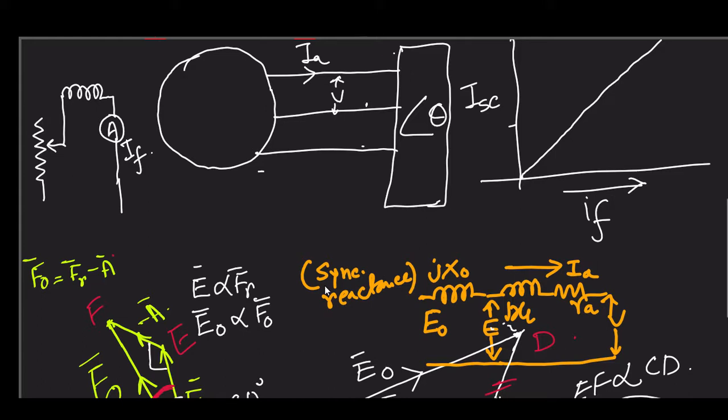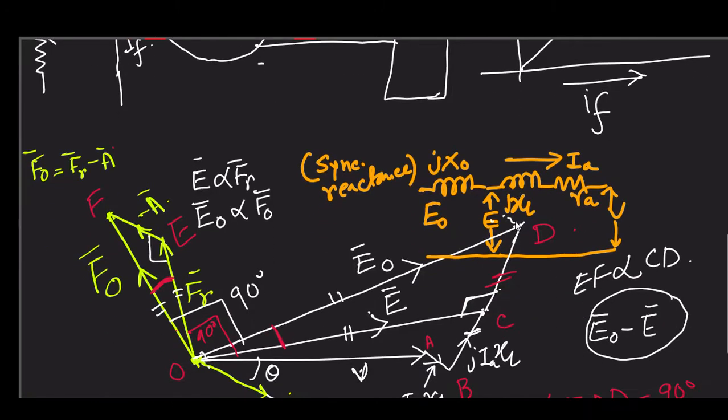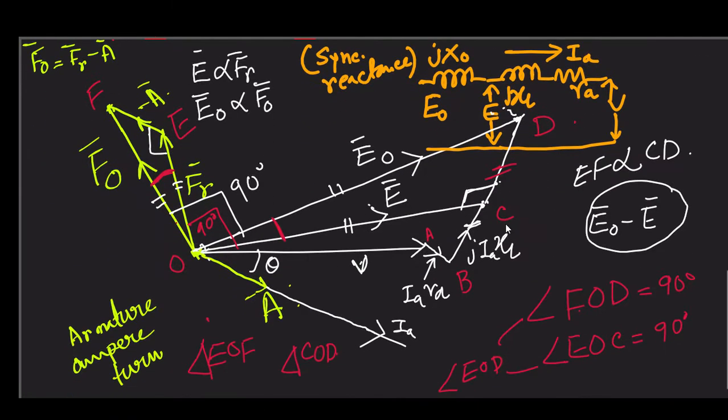As we know, the synchronous machine stator winding can always be represented by means of a resistor and an inductor. We consider that it contains only two elements, armature resistance and leakage reactance.